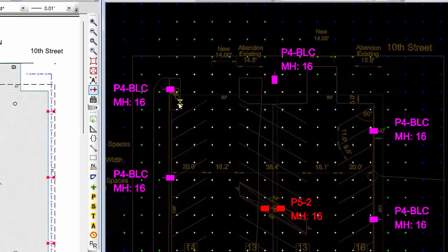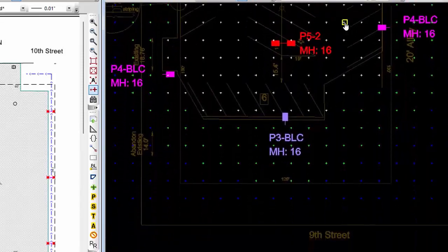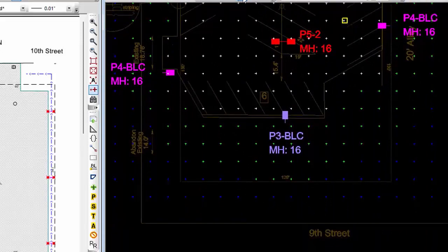So I'm going to use the property line, and I'm going to come over and select that corner of the property line right there. That tells me that's point 1. Let's get that corner, point 2. Let's pan down to the southern end. And calibrations work best if I try to encompass the area I'm working on. So I don't want to have my points right close together necessarily. I want to feel like I'm picking up a reasonable proximity for the whole project here. And then the prompt says, right click when I've selected the points.